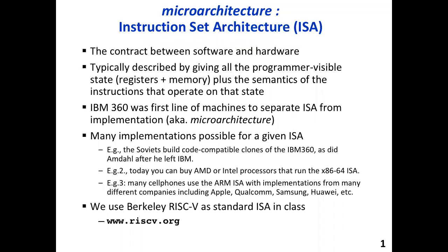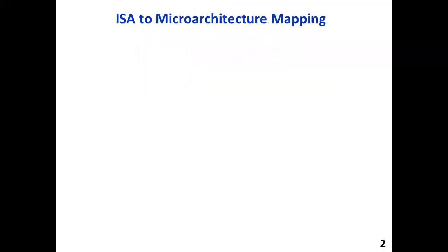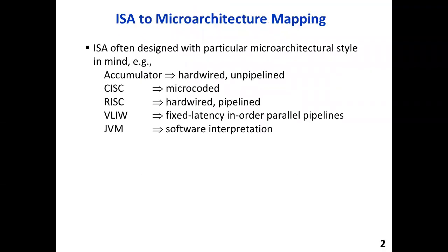So microcode has permeated most of the CPUs that we encounter today. The CISC, of course, we would like to see microcoded because the instruction set is so complicated. The RISC, on the other hand, can be hardwired, and therefore, because of its pipeline and its hardwired nature, can execute one instruction per clock cycle or faster, depending upon how deep the pipeline is.